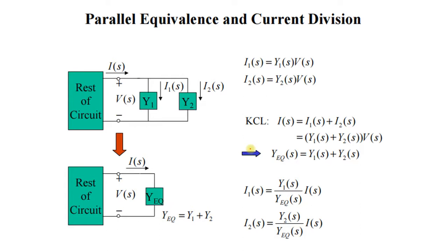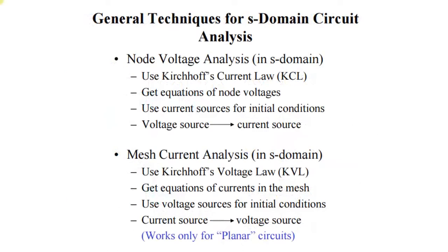And similarly, whatever theorems we used are also applicable in the Laplace domain. We use nodal analysis and mesh current analysis, all the same as what we used in the DC circuits. Mesh analysis is possible only if the circuit is a planar circuit. If it is non-planar, it is not applicable in the s domain.